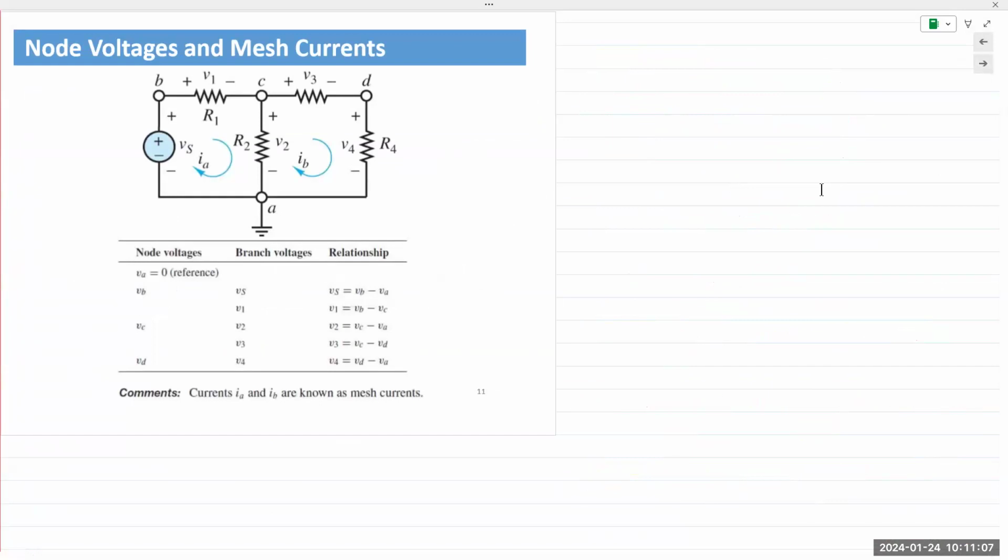These are the final two big analysis techniques in this chapter, but there's still a long way to go. These build off of the techniques that we have learned previously. Now, Ohm's law, KCL, KVL. We'll use those to write out equations which have unknown variables. And the unknown variables, in our case, are basically the voltages and currents that appear in the circuit. So, node voltage analysis and mesh current analysis, again, the point is to solve for the unknown voltages and currents.